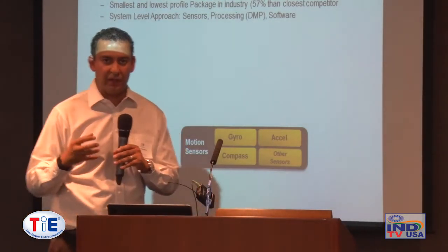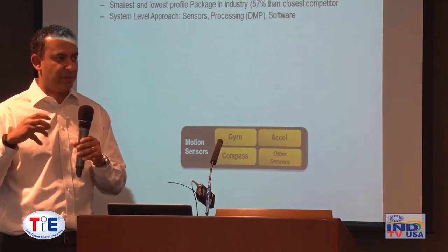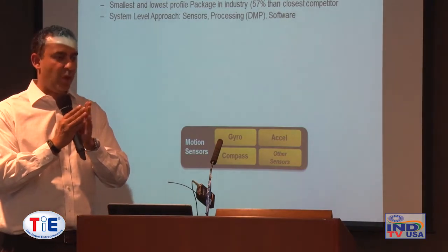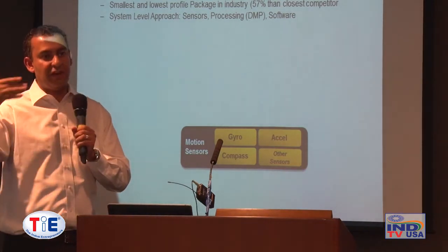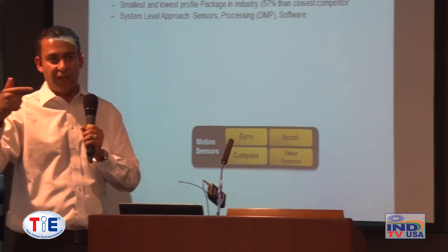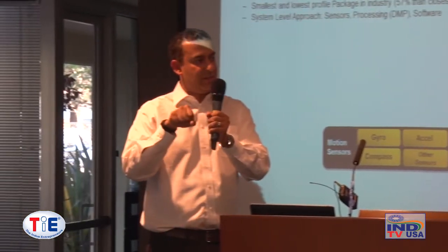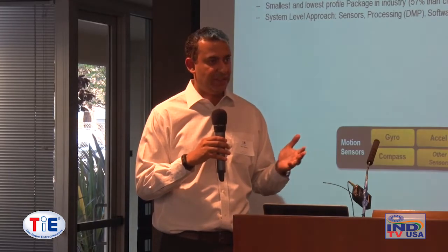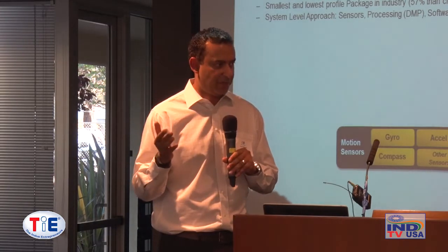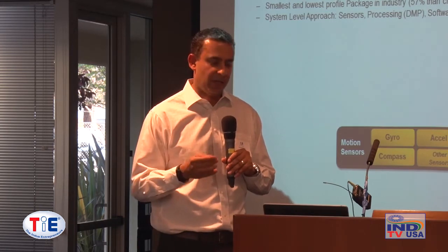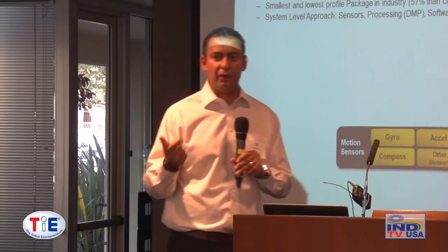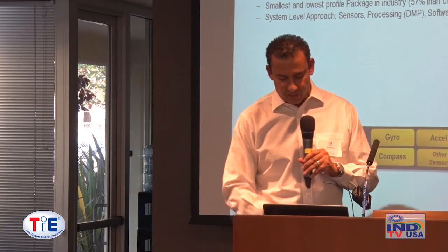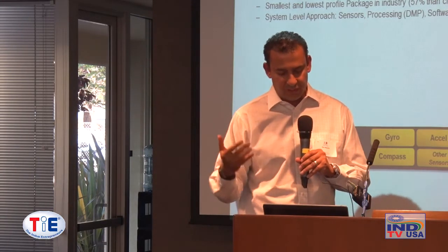What our competitors are doing, we call them skyscrapers. They're taking an accelerometer MEMS die with a CMOS for the accelerometer, wire bonding them together. Then taking the gyro MEMS with the CMOS for that gyro, wire bonding them together, then putting the 6-axis in a package, wire bonding them together. So a 6-axis product from ST has over 50 wire bonds, okay? We have something like 4, 5, or 6, okay? So with fewer wire bonds, you have higher reliability, lower power, less noise. All this stuff helps our sensor performance beat our competitors. So we're really good at integrating multiple sensors in a single die.